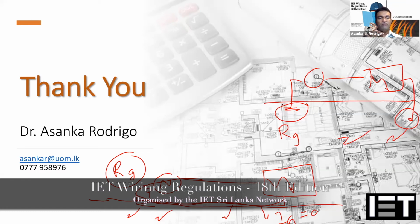That's why, in a high frequency or harmonic rich environment, there are different types of RCDs. For example, the type B RCD will basically handle the high frequency component. Also, certain manufacturers are coming up with RCDs with harmonic filters, where they eliminate this high frequency harmonic component and only look at the low frequency component, so that nuisance tripping will not happen if you are using the correct type of RCD. But if you go with a normal RCD, like a normal AC or sinusoidal waveform RCD, it may give nuisance tripping with LEDs due to this harmonic leakage current.